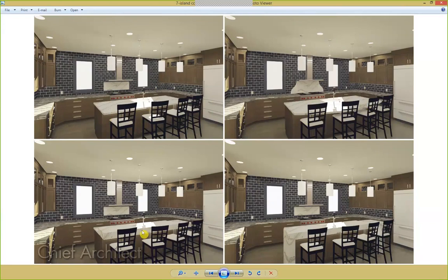We'll press undo a couple of times to get back to this step. And then we'll take a look at waterfalling. So 4 options here with the island countertops. Another option you might have observed from the photo is our backsplash. There's the bell-shaped backsplash we made as an option. And then there's also an option which has a wall niche behind the range as well. So let's first start this by adding our island into the plan.